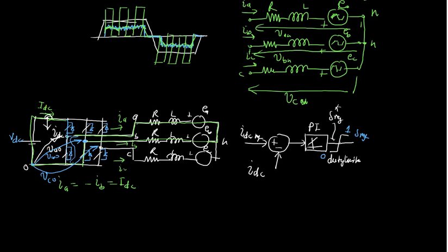So what we do here is try to generate these PWM pulses. How to generate? You remember that I explained that I consider a triangular waveform carrier signal, then we put a line and compare it. It's the same thing I am going to do here. So here you will be using a carrier signal like this.